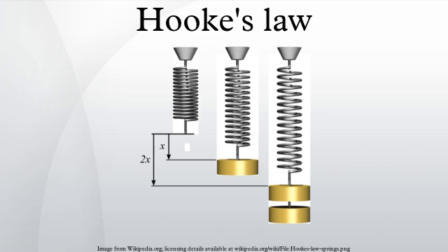In this general form, Hooke's law and Newton's laws of static equilibrium make it possible to deduce the relation between strain and stress for complex objects in terms of intrinsic properties of the materials it is made of. For example, one can deduce that a homogeneous rod with uniform cross-section will behave like a simple spring when stretched, with a stiffness directly proportional to its cross-section area and inversely proportional to its length.